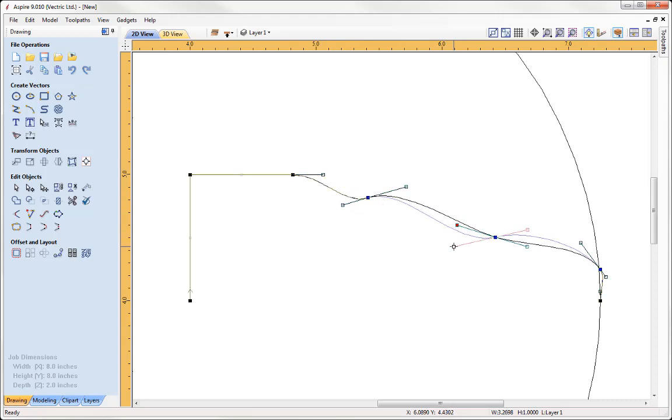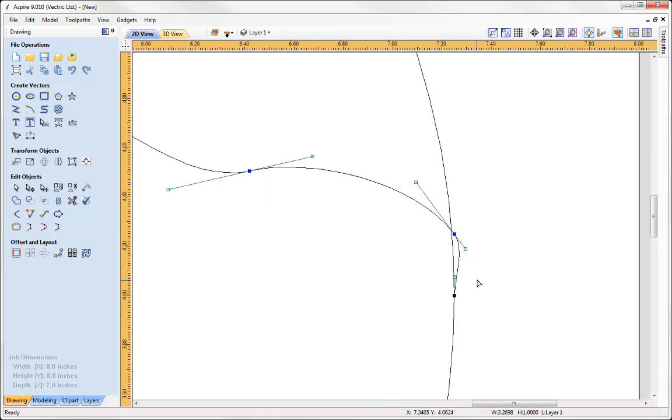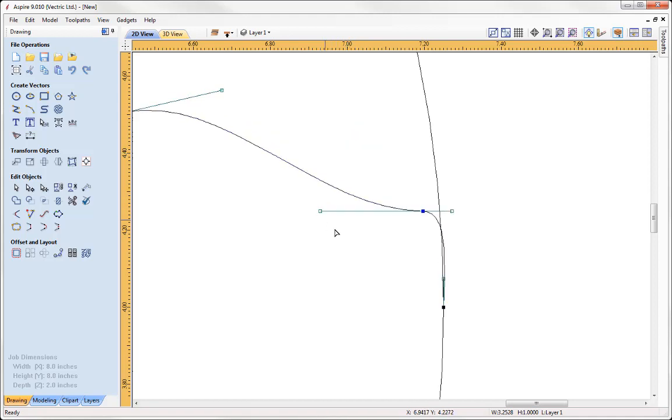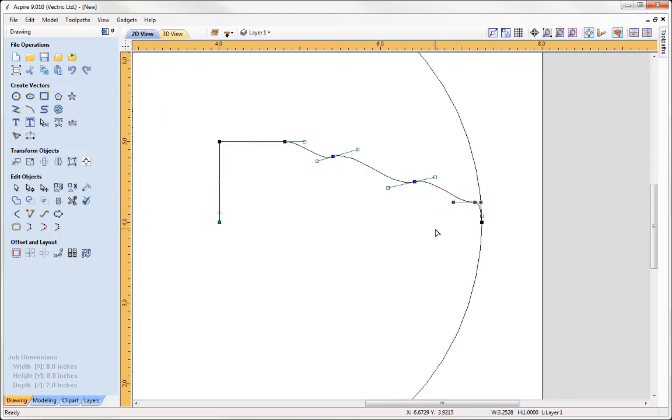We'll do the same over here, so just creating a little bit of a wavy pattern here. And then over to the right hand side, I want to ensure that we keep that inside of our circle there, and I'm going to pull on this handle so it's aligned in X like so, and again we're just going to move that over so that it sits within our circle. Okay, so that is our curvature for the underside of our bowl.